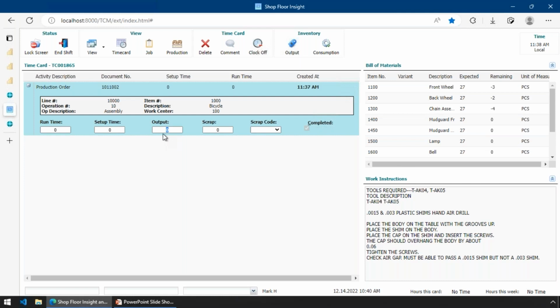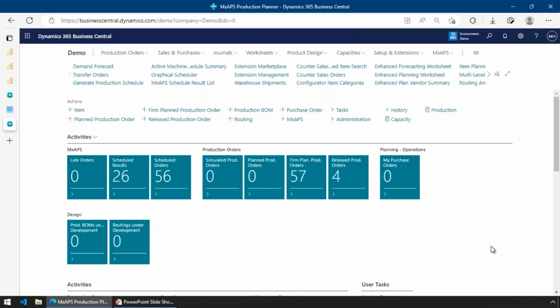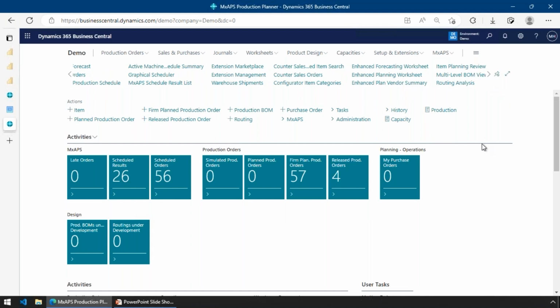Okay, so it's very important that we're able to get that feedback from the shop floor so that your schedules are realistic. And one other quick note on that, when we have realistic labor times coming in from the shop floor, it allows you to do some analysis like, are my expected run times accurate? Am I actually scheduling things appropriately? Maybe I've set something up that says, oh, it takes 2 hours to run, but in reality, it's taking 3 hours, and I'm wondering why we're never meeting our schedule. Well, it's because my routing's wrong, my expected time's wrong.